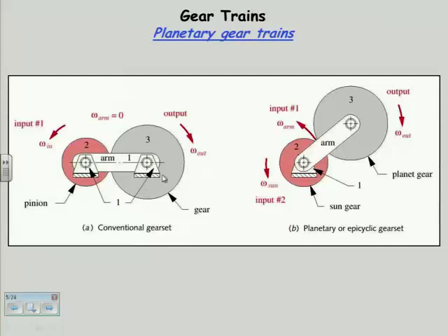But if I represent that physically, and then I pull this pin away from the ground, that is, I take away this grounding pivot, then I'm able to rotate that assembly, namely the arm and gear 3, around gear 2. And now I have 2 degrees of freedom.